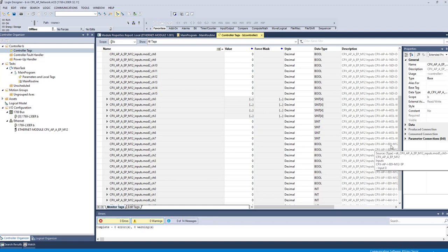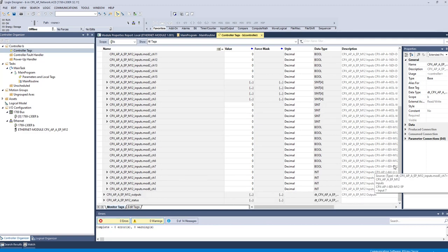The first of the decentralized has again 8 bools for an 8 input module. And coming after it, we defined an analog module. So instead of having a bool or even a cint, now we're using ints, because that would be the better data type to use with an analog module.